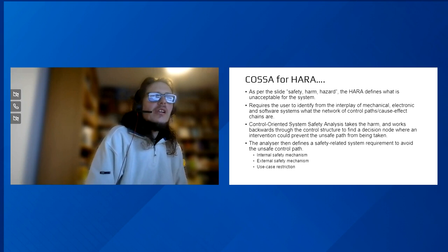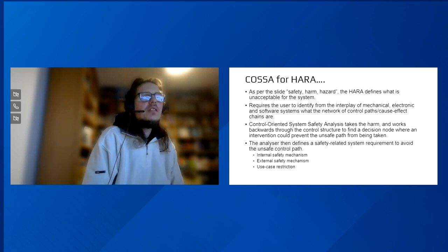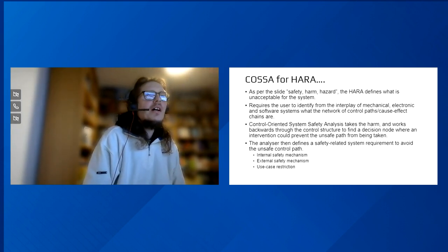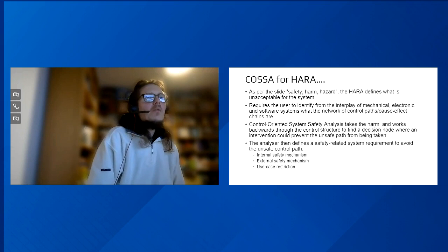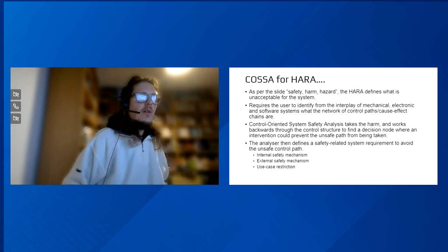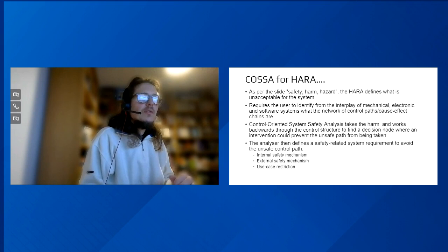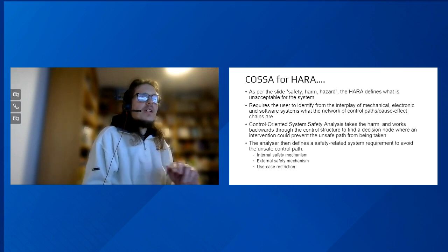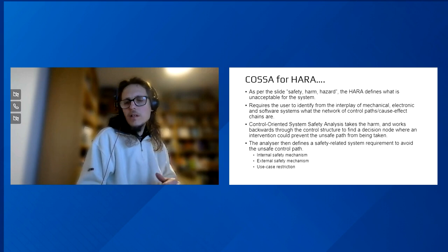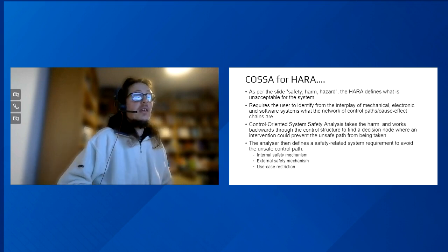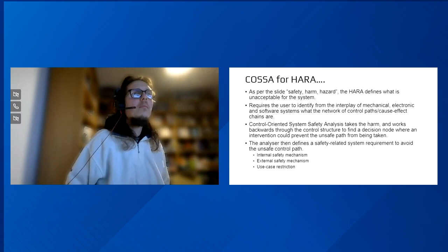Now, this could be an internal safety mechanism where we construct something within the hardware to keep us in a safe state. It could be an external safety mechanism where, if our hardware is used as part of a bigger system, the system detects that the hardware has gone wrong, or it could be software, which is periodically running something to check for the safe running of your system, or it could be a use case restriction where you tell the user they shall avoid using the device under certain conditions or in a certain way.